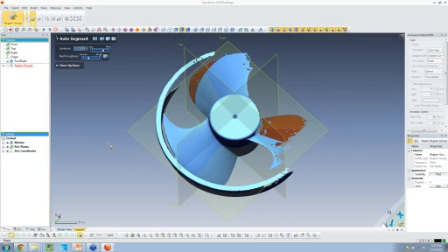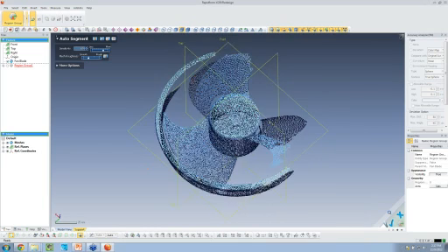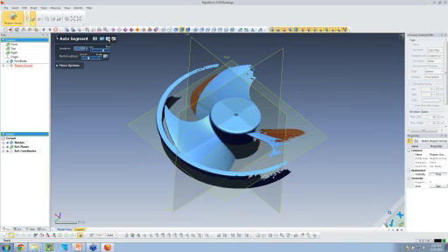So what I'm going to do first is what we call a region group. A region group is going to offer a grouping of features on this part. These features are our ability to look at this part, look at the curvature of the information that's on the part, and dissect it a little bit further to see if we can extract some CAD style features. Not to say that this is particularly CAD at this point. What we're doing is we're still looking purely at the point cloud level, and we're trying to offer some intelligence associated to that point cloud.